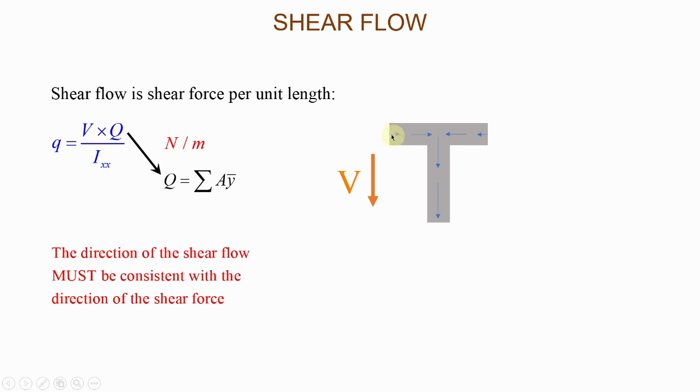Okay, but you do not need to divide your calculations like that. You can just do a similar thing to what we did when we were calculating shear stress, and you can just try to find what will be the shear flow here, by using the top area here and also the distance of this top area from the neutral axis of this section.